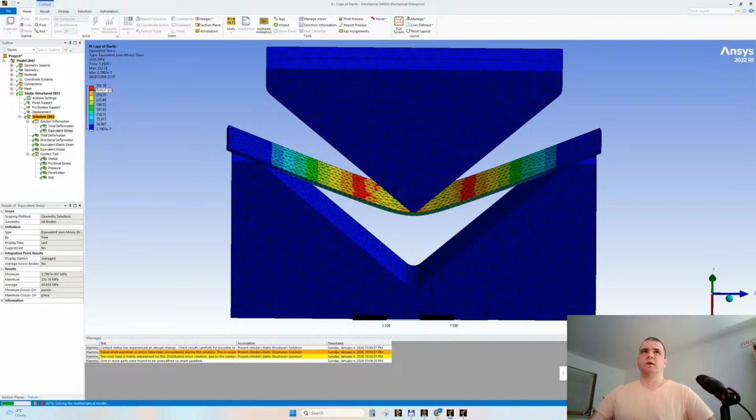So a golden rule, if you want reliable stress values, you need to almost always use nonlinearly defined materials, because it will allow isotropic hardening, a local hardening.